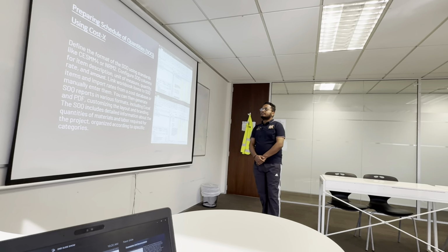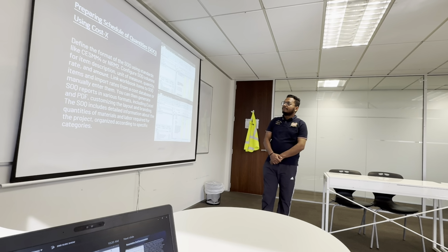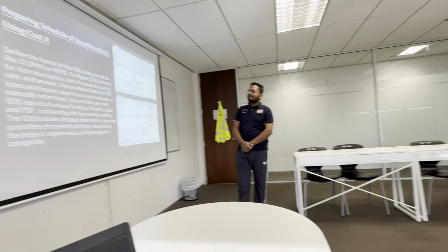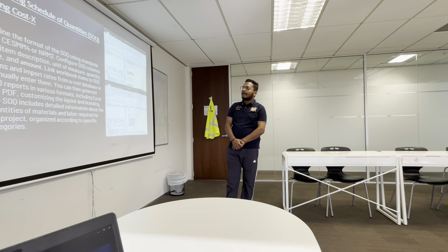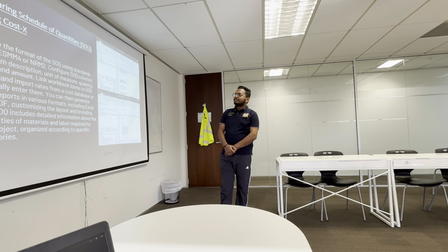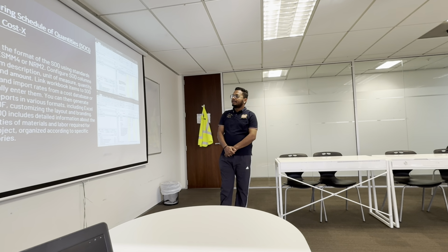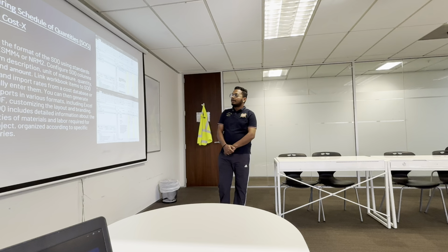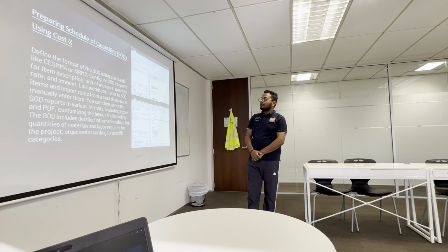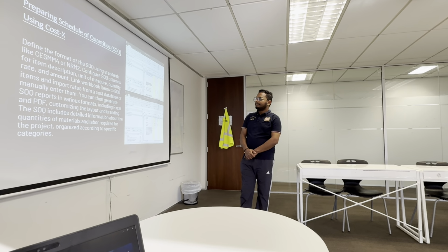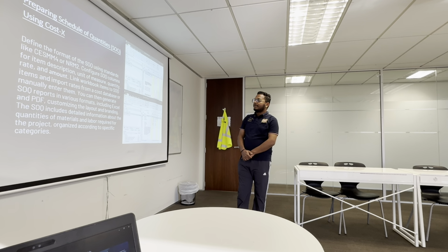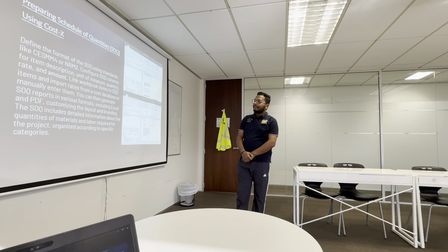Preparing a schedule of quantities, SOQ, using Costex. Define the format of the SOQ using standards like CESMM4 or NRM2. Configure SOQ columns for item description, unit of measure, quantities, rates, and amounts. Link workbook items to SOQ items. Import rates from a cost database or manually enter them. You can then generate SOQ reports in various formats, including Excel or PDF.